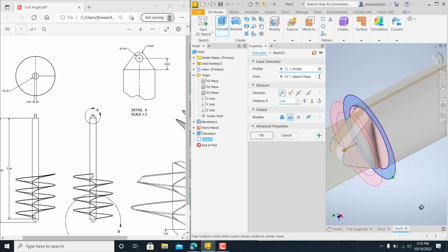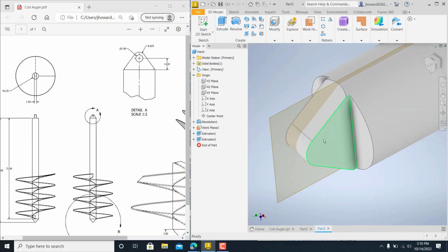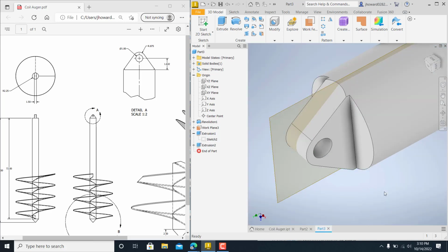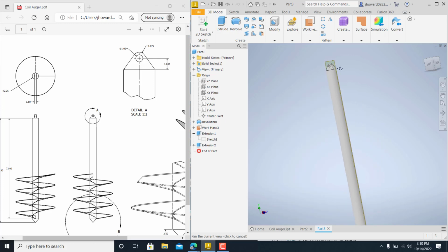Oh, it was going back the other way. I'm sorry, it was right. I flipped it back the other way. So that's what it should look like. Oh, we missed the hole there. So if we missed that, it's easy. Go back here, just double click the extrusion, and whenever we hit profiles, take that profile off, and now catch it again, midpoint between the planes. Okay, that looks a little better, doesn't it? Okay, so we got that out of the way.